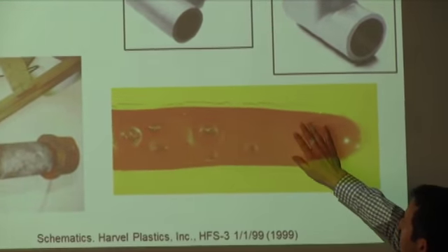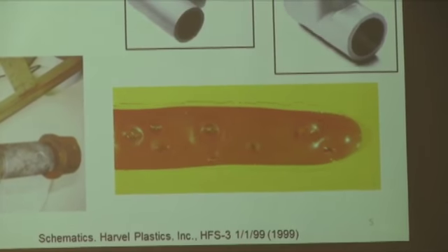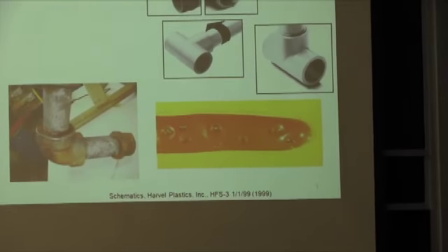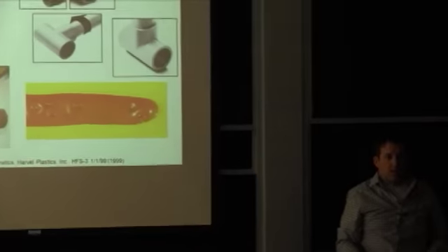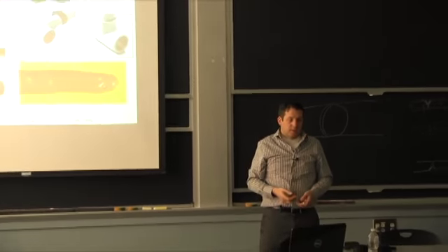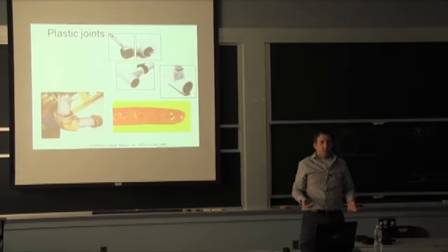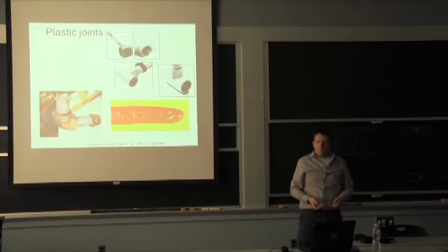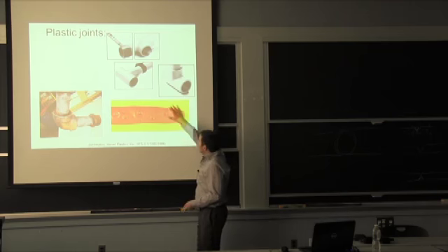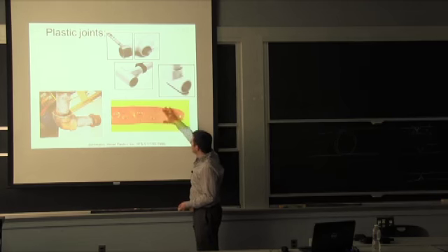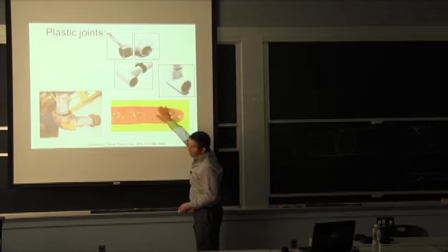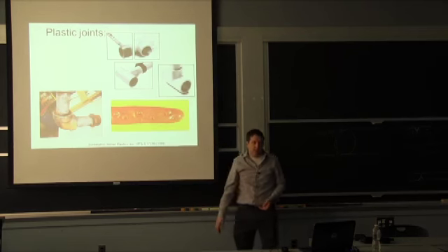This drip is not something that you want, but it comes if you're putting too much of it and if you're not wiping it off. What happens in those conditions is that the solvents are degrading your plastic, and if you have some shrinkage force here, it creates the tension to initiate cracks.